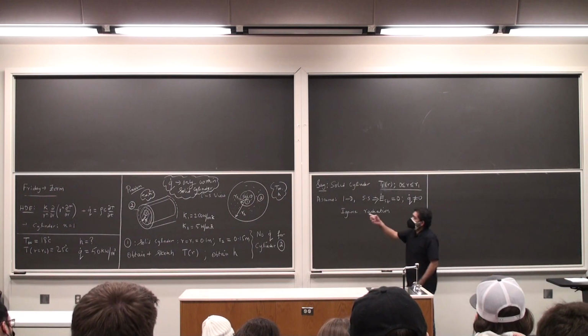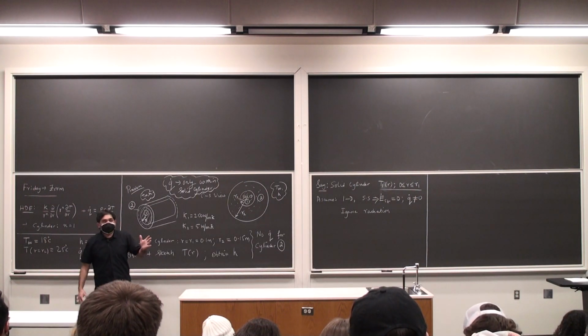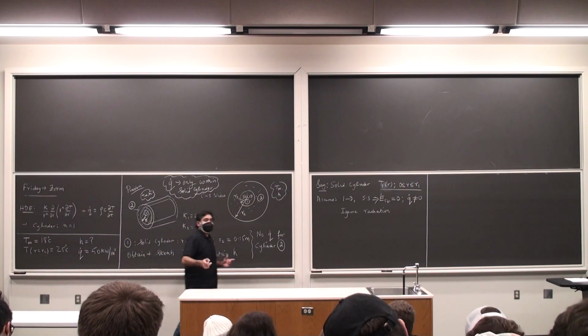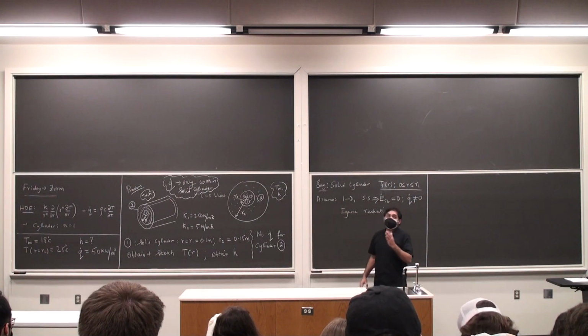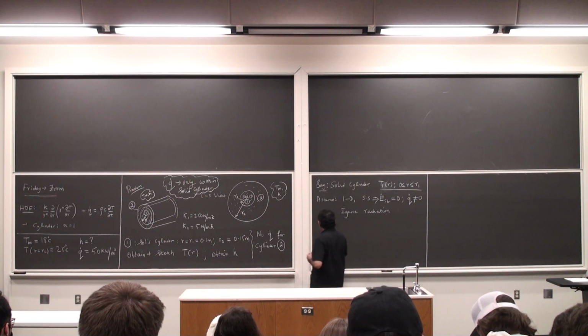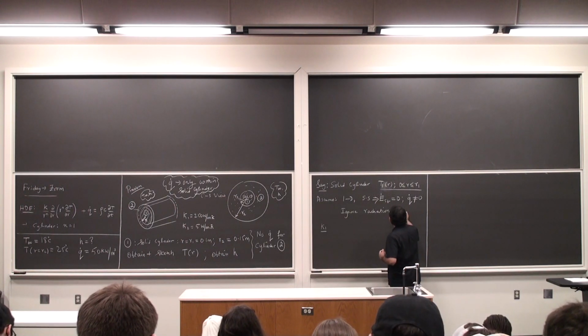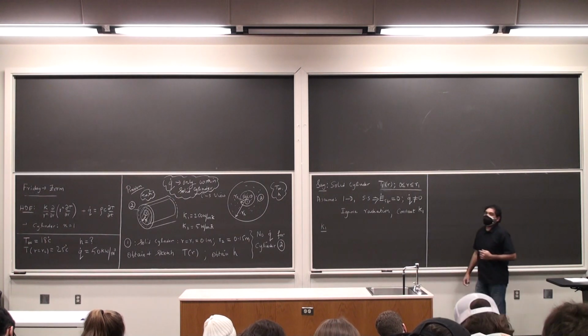With these assumptions, using the fact that n is equal to 1, I set up the heat diffusion equation, integrate it twice, and get the temperature profile in terms of some constants, which we did last class, but I'm going to do it again very quickly. I'm going to say that the thermal conductivity is K1, so I have constant thermal conductivity. That's another assumption that you're making here.